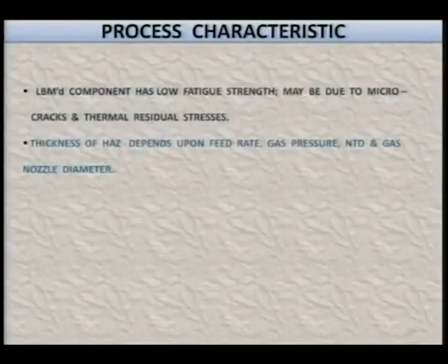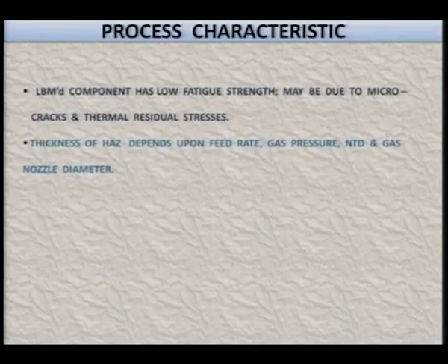Another point is that the thickness of the heat affected zone, HAZ, depends upon feed rate, that is the relative motion between the laser beam and the workpiece, gas pressure, nozzle tip distance, that is the focal point length, and sometimes also the focal point length, but not necessarily at every time that the nozzle tip distance is equal to the focal point length, no, and gas nozzle diameter. They also decide the thickness of the heat affected zone.